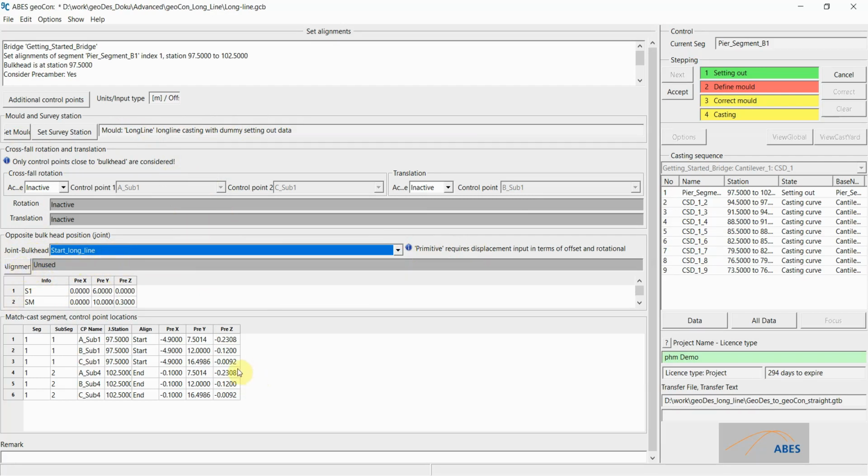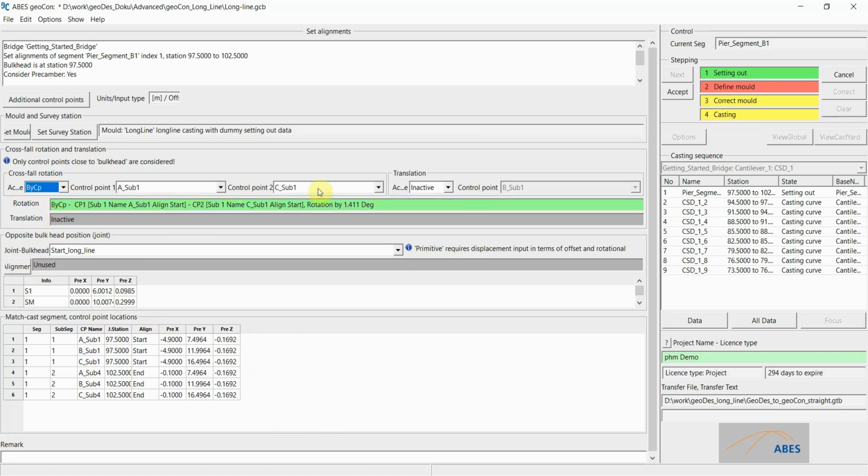And because obviously there is a crossfall here, we are going to turn the surface of our segments to horizontal. The Z's are now both 0, and I'm assuming that this crossfall rotation translation menu up here is known to my viewers here.